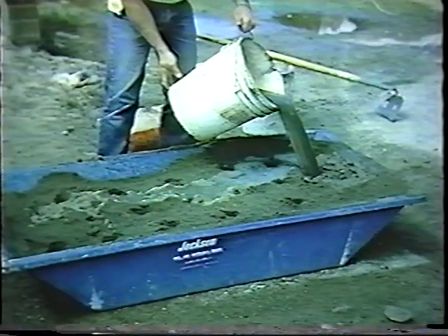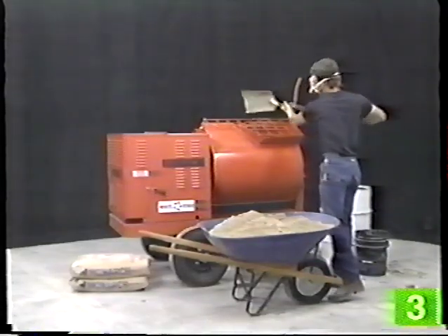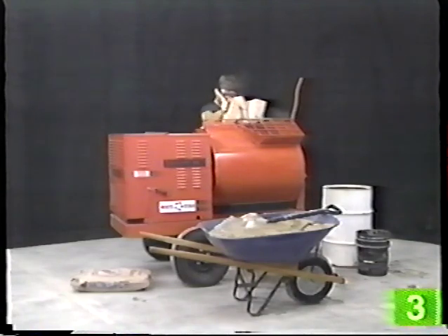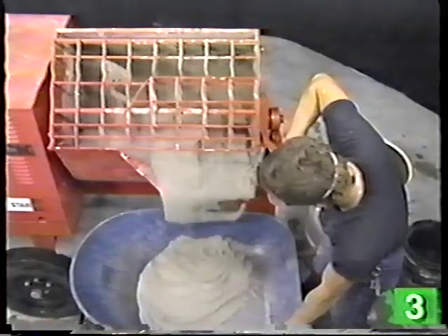Of course, you must add enough water to the mortar to provide a good working consistency. The mason will usually know the right amount of water to use. Always add materials to the mixer in the same sequence, and fill the mixer to the same level to give consistent mortar. This is especially true of colored mortars.